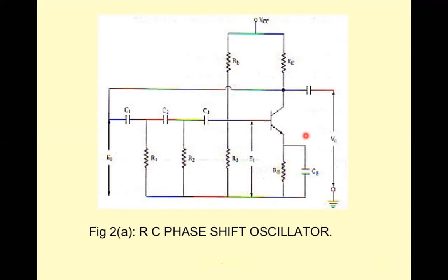So the transistor basically is used as an amplifier as well as a switch. For switching, we have studied the cutoff region, saturation region, and active region. The region between the cutoff region and the saturation region is the active region. If the transistor is fully off, it is the cutoff region. If it is fully on, it is the saturation region. So we have studied the transistor as a switch over there.